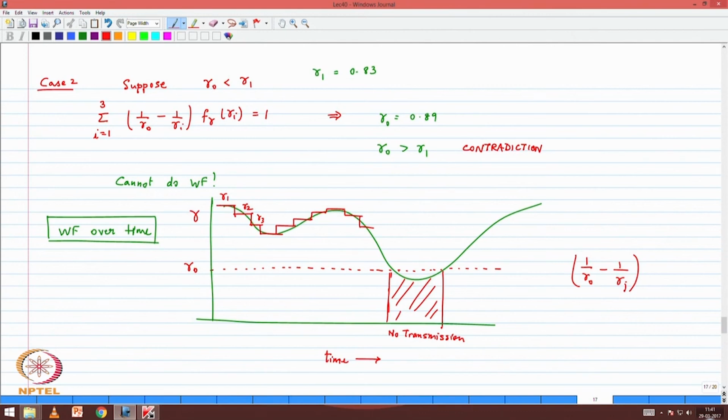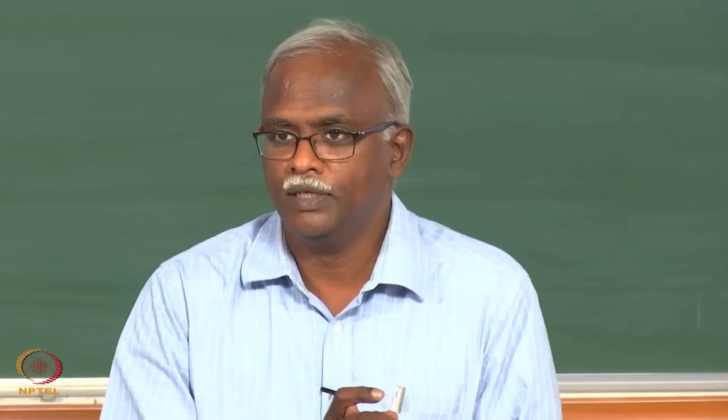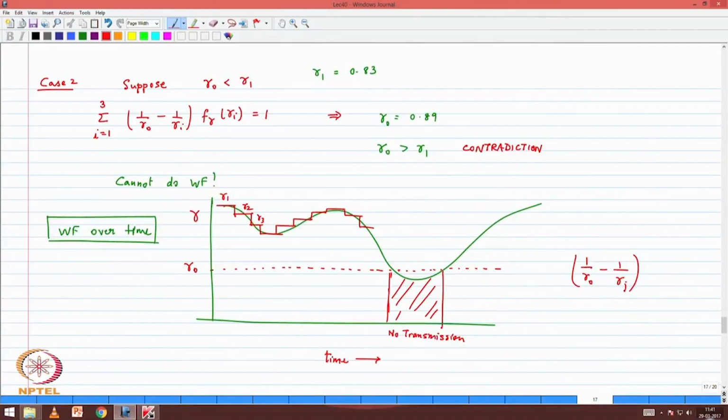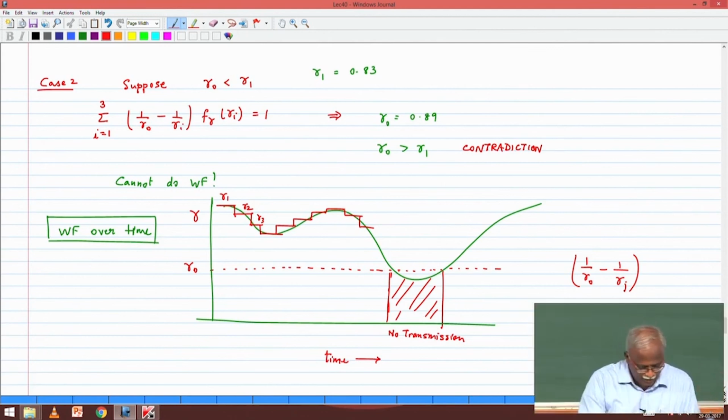So, how can I get the maximum out of a fading channel? By discretizing my SNRs, and for each of these discretized values of SNR, I have an optimum encoder decoder pair. Water filling tells me, based on my average power allocation, how much power I should allocate for the different SNRs. I use that information also and get the maximum in terms of the capacity.